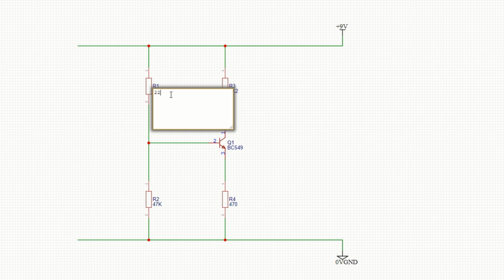Again, it's approximations, but that should give a somewhat reasonable voltage on the base of the transistor to make it work in a linear range. Without using odd values, it may not be exact, but sorry, I've got a dry throat. It may not be exact, but it should be near enough to put it in a decent working linear range.